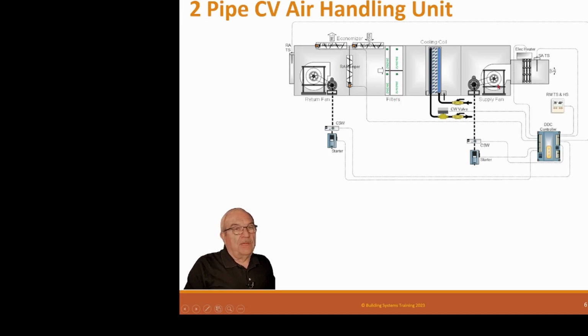Now what's a little bit different, because this is a constant volume unit, remember, we're still talking constant volume, so fans are constant volume, so the airflow volume does not change. We have a coil here for the chill water coil. Now again, remember, when you take the system for chill water, you'll notice a lot more. But one of the most important things on these is that the supply water, which is this one right here, always enters at the leaving side of the coil.